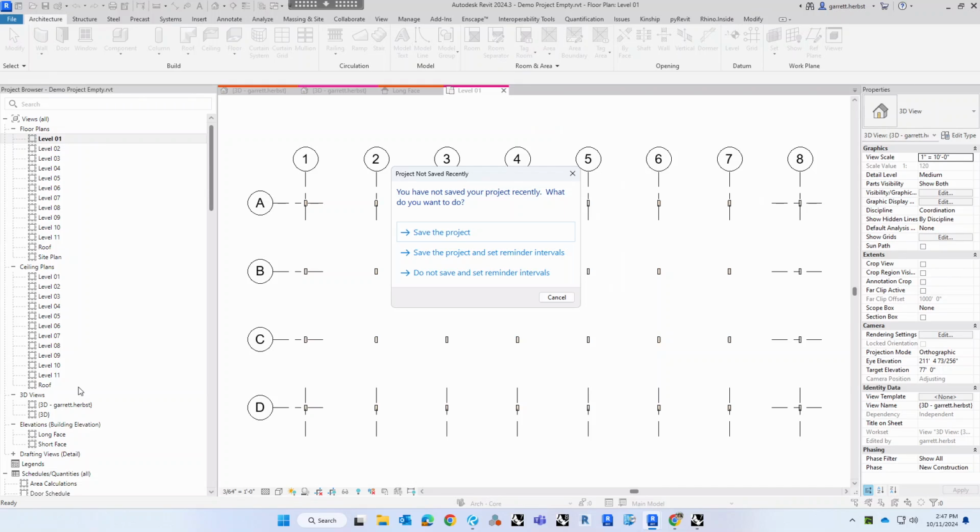You can also do shear walls. They act very similar. However, just be aware that shear walls are not just walls. They typically have some sort of tails on them, so they create C shapes essentially so that they're a little bit stiffer. So when you're doing diagonal bracing, I almost always will model it in elevation. I just got to adjust my view.